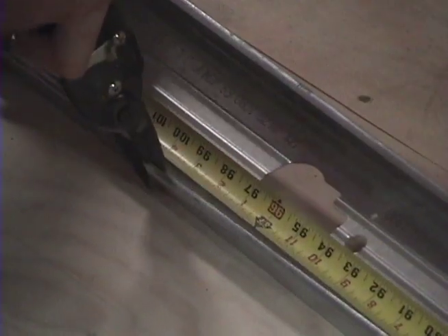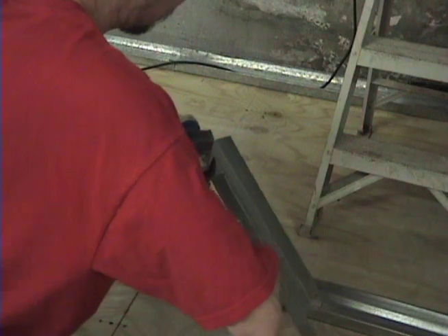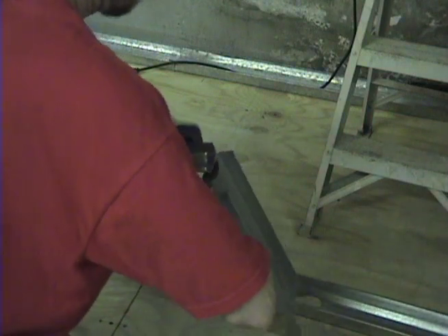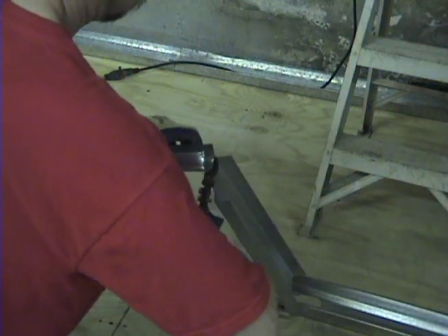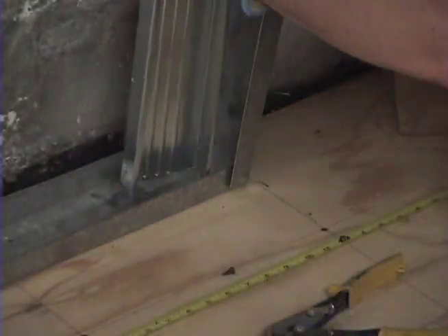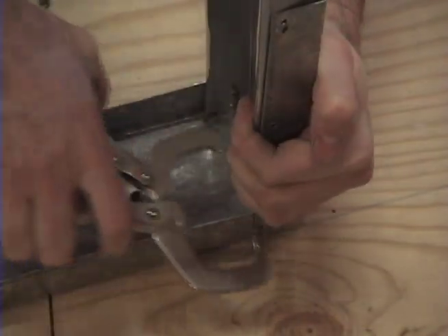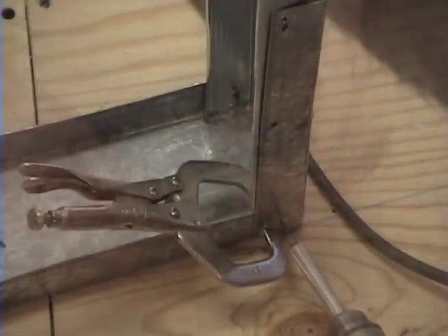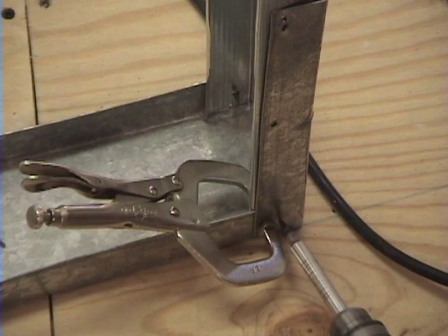Once you have your measurement, you snip both sides with tin snips, and then cut through the middle by curling the studs with your free hand. This makes it easier to cut all the way through. Place the stud in the right angle end of the base plate as shown. Hold it together with this special vice grip, then fasten it with 1/2 inch number 8 panhead screws.